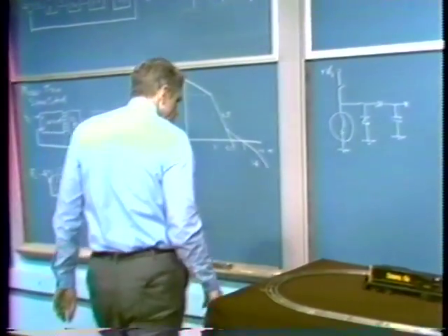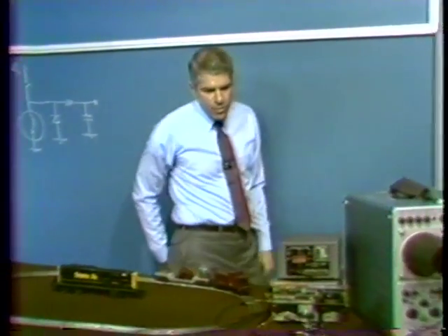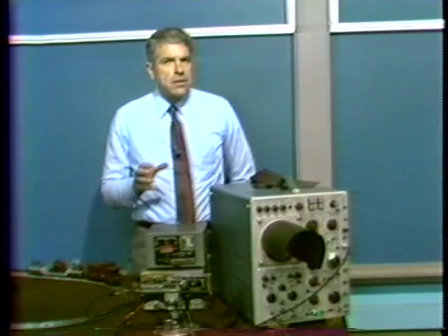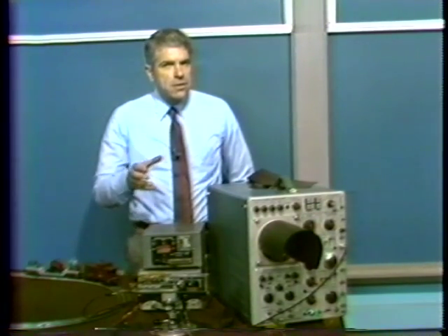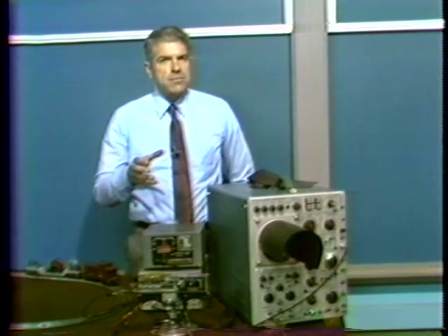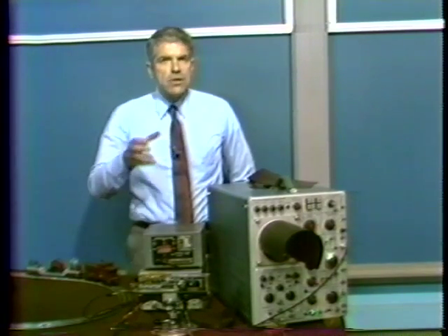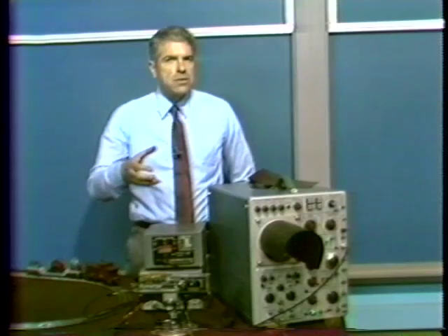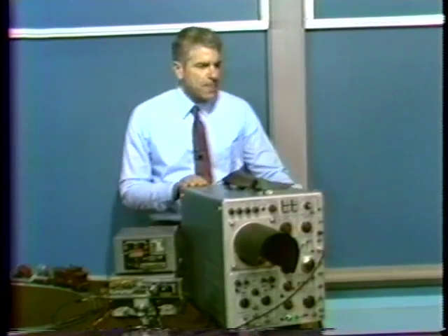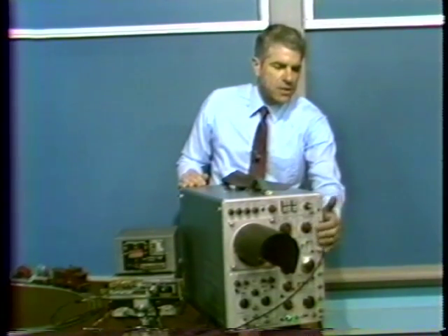And now we can notice a very different nature and a very different behavior to the system. We can hear it. We don't have to, as yet, look at the oscilloscope trace. We can actually hear the engine pulsating. There's the startup transient, and we hear it pulsating. We didn't hear that before. When we had the system adequately compensated, we didn't hear it. You can actually hear the speed changes, the overshoots. We can show the same thing a little bit more scientifically if we now look at the speed transient, look at motor velocity.